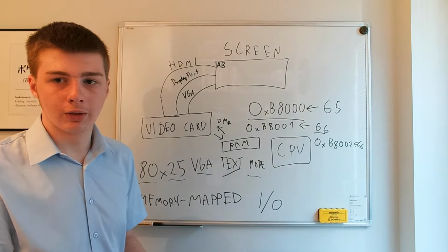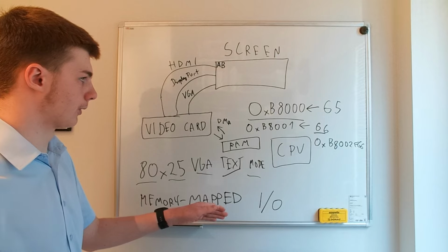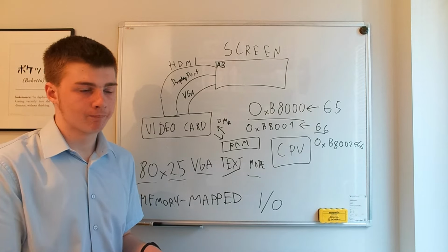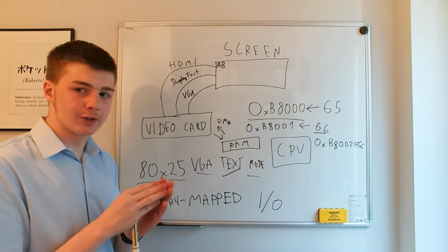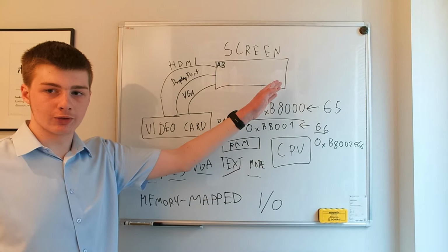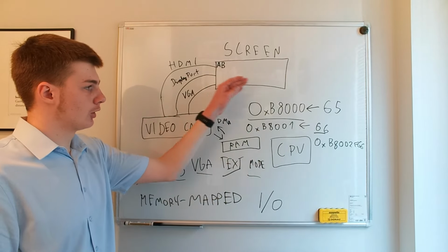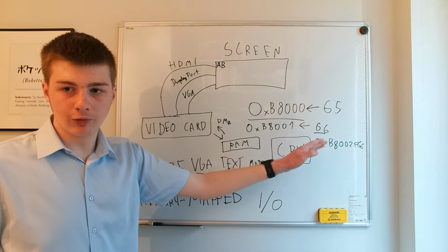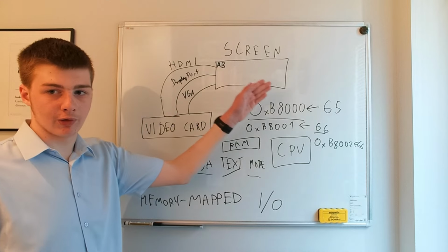So, to provide a more general protocol: check where the base address of a buffer is. You make a pointer to that base address. Then you see what the format is of the information in the buffer and what it corresponds to, the actual peripheral or extension card that you're using. Then you fill those values in the buffer using the pointer, to get what you desire.